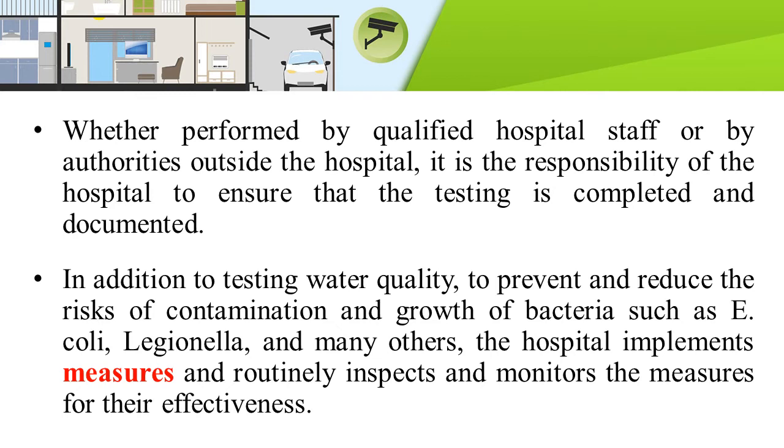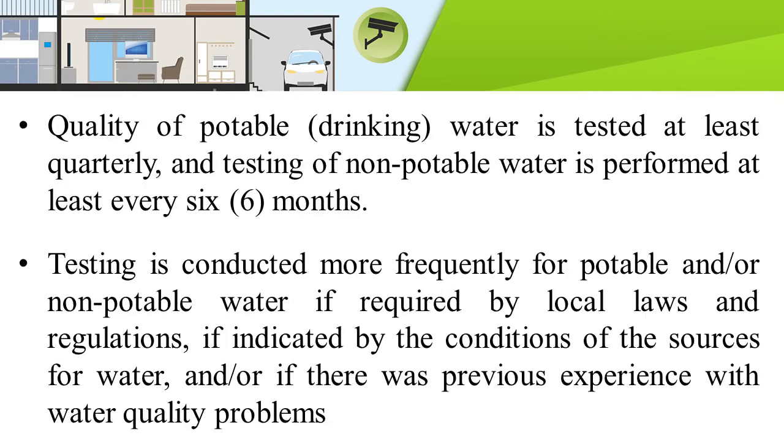In addition to testing water quality to prevent and reduce risks of contamination and growth of bacteria, the hospital implements measures and routinely inspects and monitors the measures for their effectiveness. Quality of potable water is tested at least quarterly, and testing of non-potable water is performed at least every 6 months.